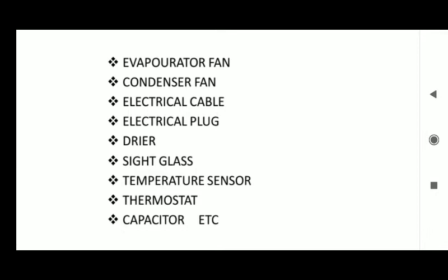Then capacitor, very, very important. This gives power to your compressor to work. If you don't have a capacitor, there's every tendency your compressor will not work. And don't forget, when we talk about compressor, we have what they call starting current and running current. Starting current for your compressor is very, very high. If your compressor is rated up to 20 amps, when you are starting it initially, the amps that it draws can be as high as 30 or 40 amps. So in order to boost your compressor, you need a capacitor that will store enough electric charge to boost up your compressor as it works.